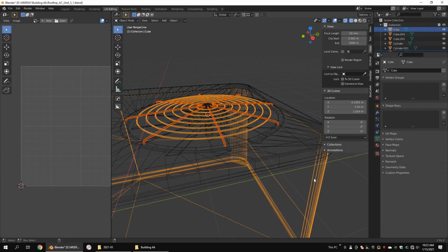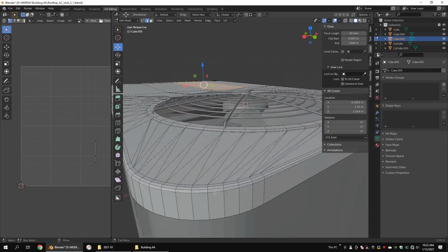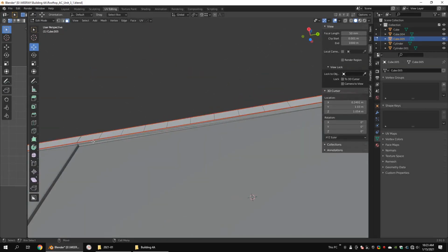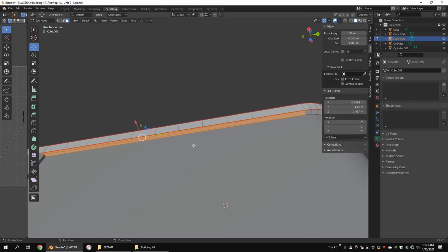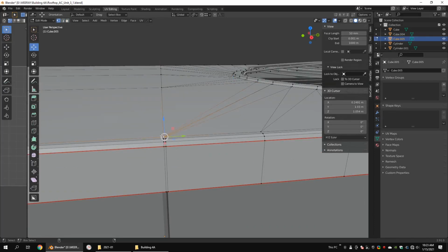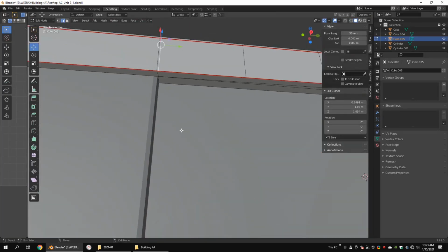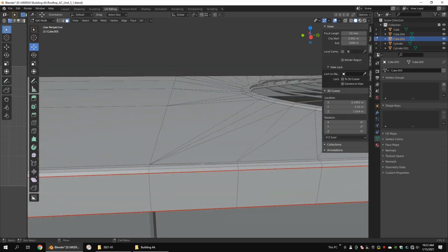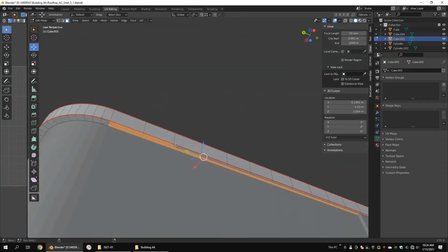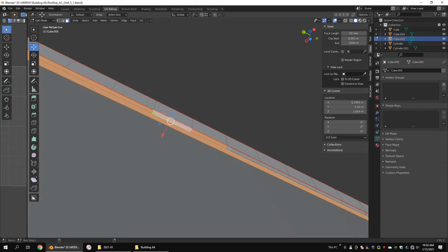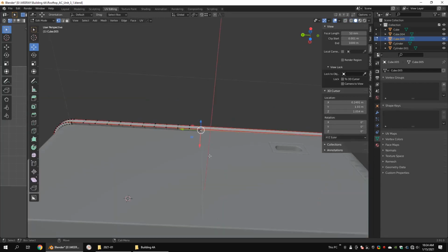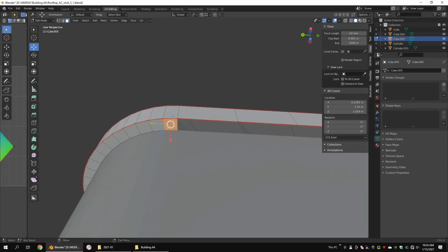You can join the objects together which have marked seams if you like. Looks like there is an end-on here. Merge the vertices. Delete the edge loop. Convert triangles to quads. Delete these end-on faces. Merge the vertex.